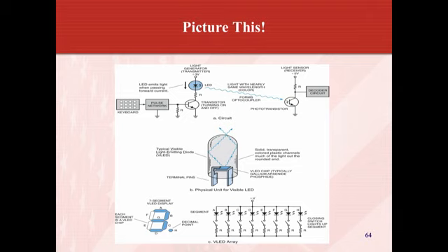And below that, they've got what they call 7-segment LEDs. They've been around for quite a while. Basically, you can put up any number, 0 through 9, by lighting up different segments, and each segment consists of an LED. Then they're showing you an LED array, which is similar to that, showing how the 7-segment display works more or less. Closing the switch lights up a segment.